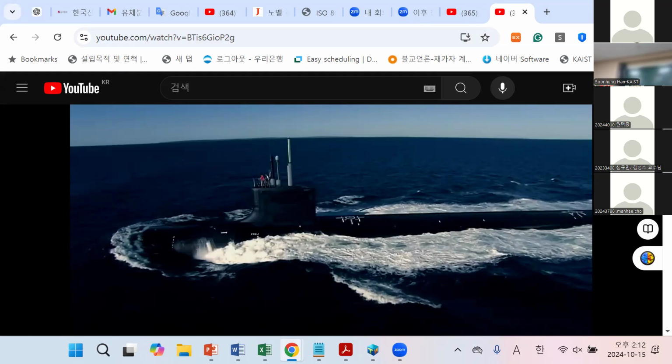But the problem is inside the ship, the acceleration is very high. Response acceleration, right? With a soft spring or hard spring, the acceleration response to the passenger is different. If the response is too high, the motion is big. With big acceleration, the passenger cannot sustain it. So you need to have very strong restraints inside the ship. But the Coast Guard needs to work in this situation. Okay, that's enough.